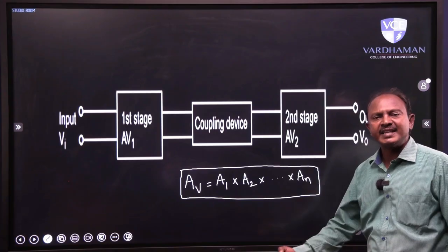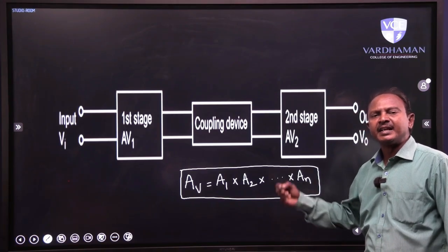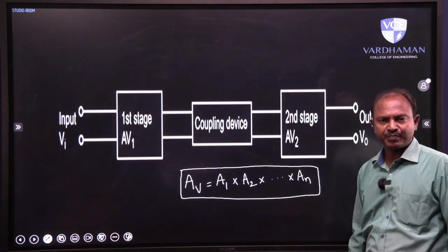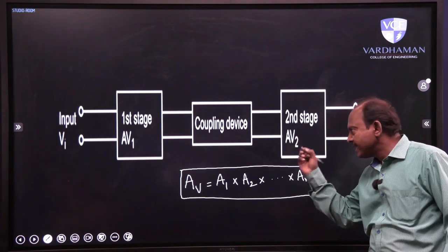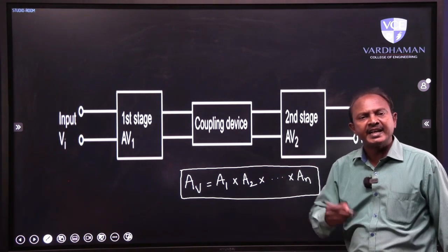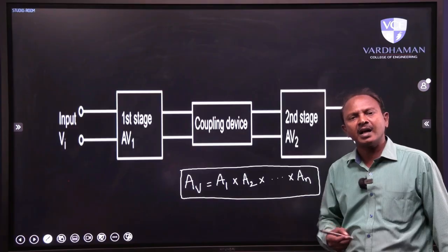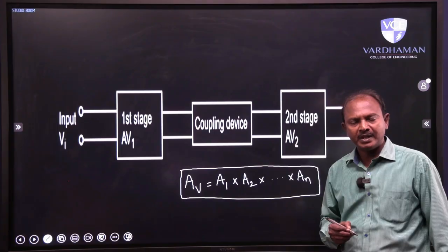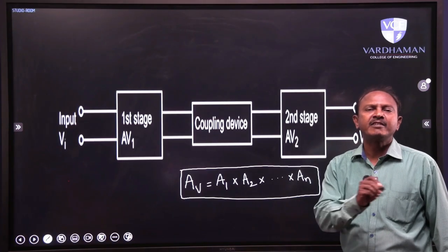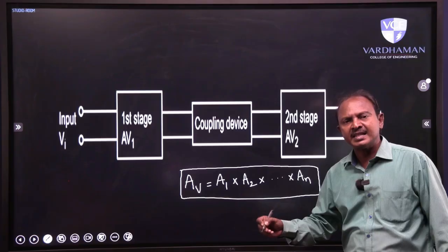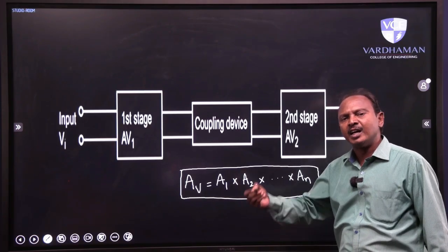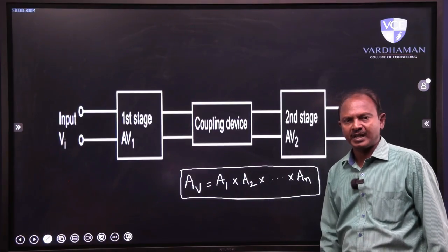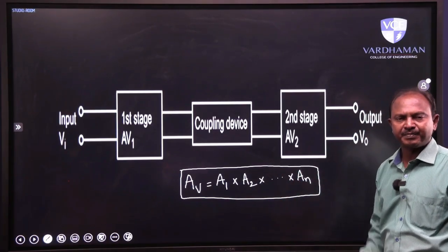As a result, one can easily understand that the gain is going to be very high. So, multi-stage amplifiers are very high gain amplifiers. The question here is, can the high gain in a multi-stage amplifier reflect in a high output voltage? No is the answer. High gain will not reflect in high output. High gain is meant for amplifying very weak signals, meaning input signals in the range of microvolts can be amplified up to a range of volts. That is what a multi-stage amplifier is meant for.